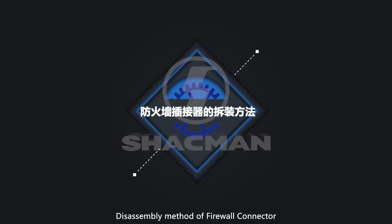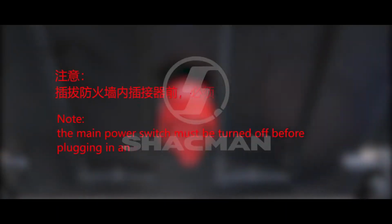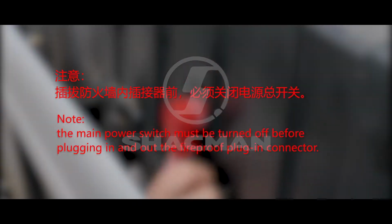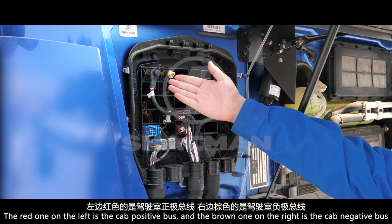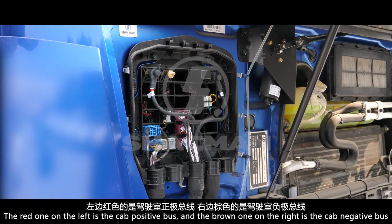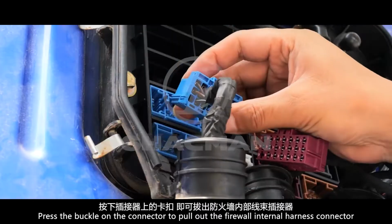Disassembly method of firewall connector. Turn off the main power switch. Note: the main power switch must be turned off before plugging in and out the fireproof plug-in connector. The red one on the left is the cab positive bus, and the brown one on the right side is the cab negative bus. Press the buckle on the connector to pull out the firewall internal harness connector.